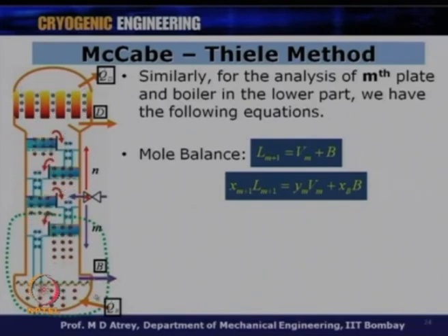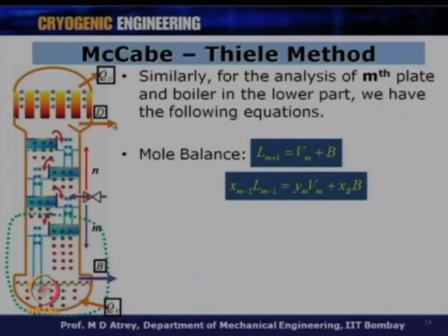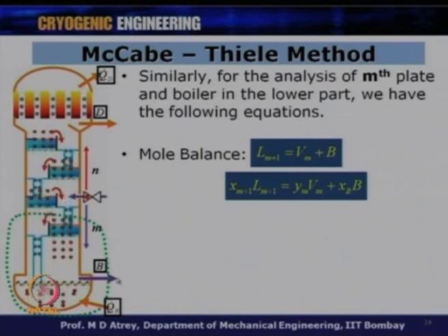As you know, Xd we have assumed to be 98%, but Xb is now going to be very small because I do not want this nitrogen to be there in oxygen. So, Xb is going to be only 0.02, 0.03 etc., right, because the purity of B has to be 97%. And I am talking about the component of nitrogen in oxygen here, and that is what Xb will denote, because we are doing mass balance for the same component over here.